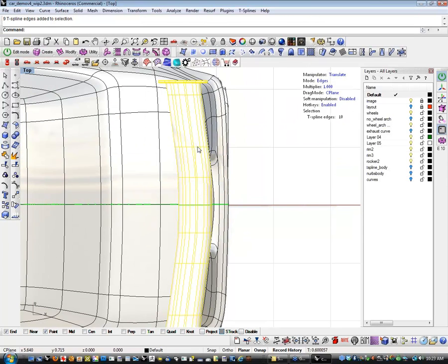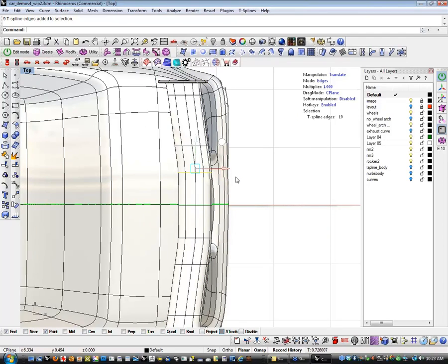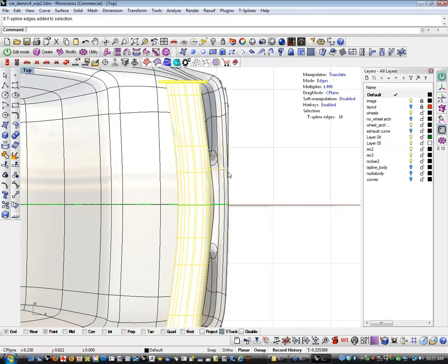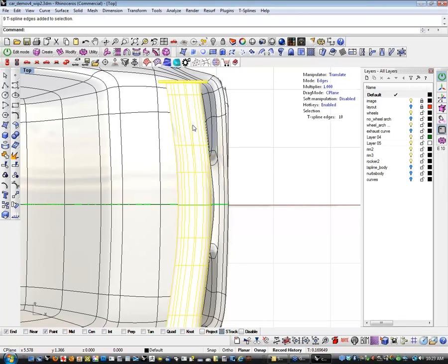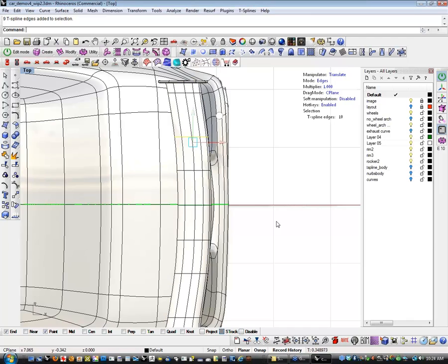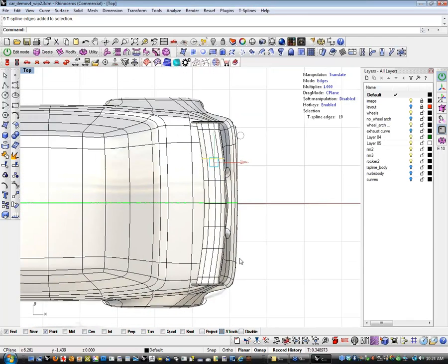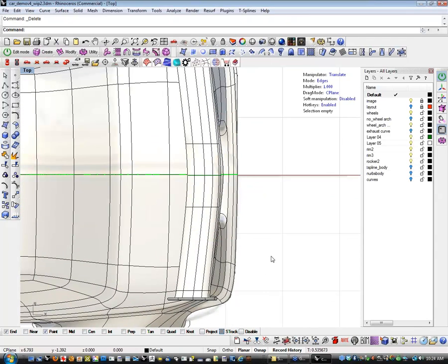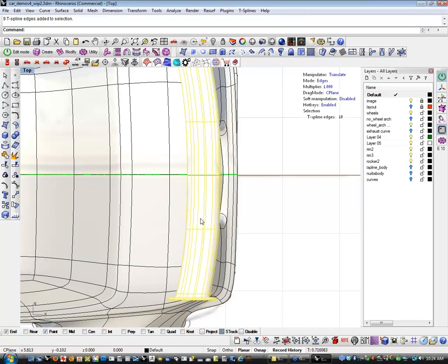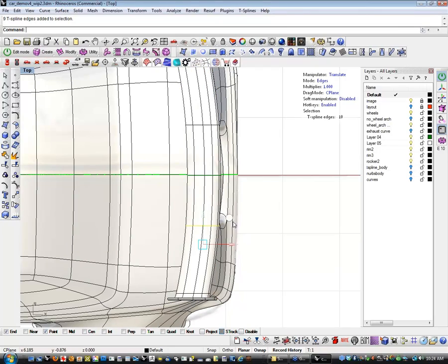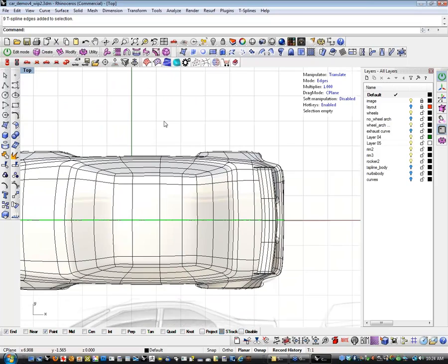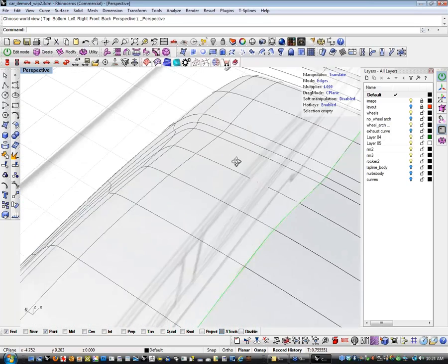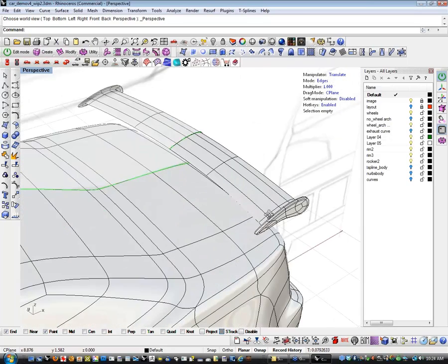And this edge probably needs to get a little farther away from the center line. As does this one. And if you have too many edges, like if there's a weird dent in here, just kill this one. Move this one out. Use it to control it like a 3-point arc. And let's sculpt on that thing just a little bit.